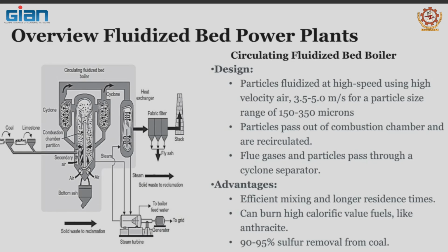This is operating under the fast fluidization regime. That means all the solid particles are entrained out of the bed. They're captured in cyclones and then returned. That's why it's a circulating bed. And then the rest is how the steam power plant operates. So you have to have higher fluidization velocities. The other thing I should mention, which is a disadvantage compared to